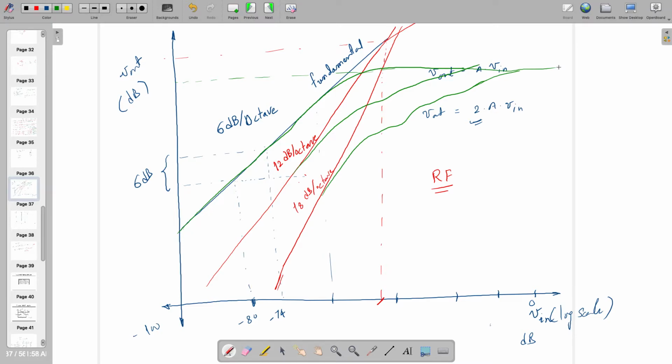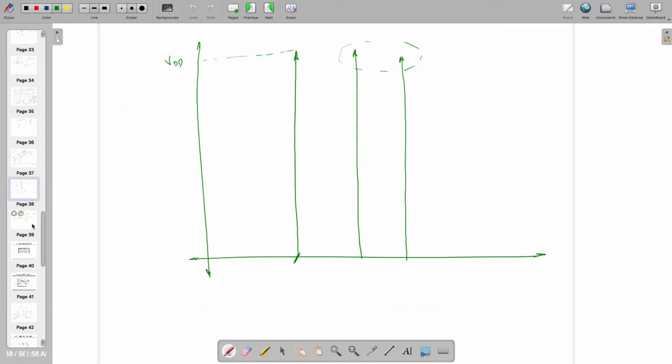Now what information do I want? There are some circuits where we apply a fundamental which is a little bit lower than VDD, but the second harmonic and third harmonic go beyond your fundamental. This might happen, meaning your badly designed circuit, right? So I need to find out the point after which the second harmonic will be higher than the fundamental, or the third harmonic will be higher than the fundamental. I need to find out that point, because I am not going to work after that point.